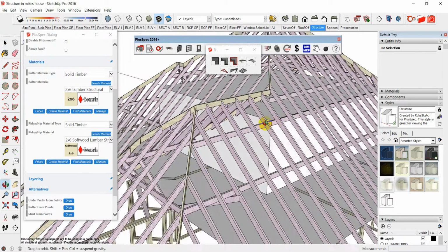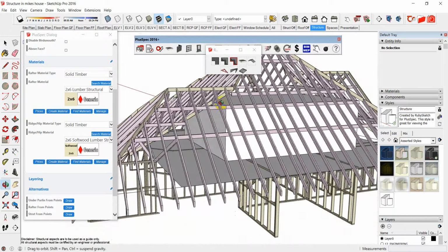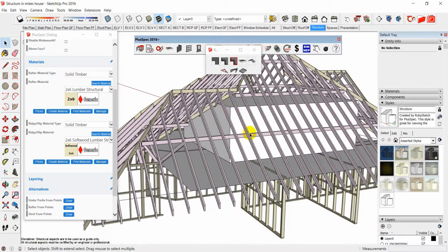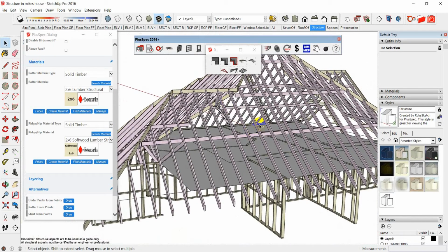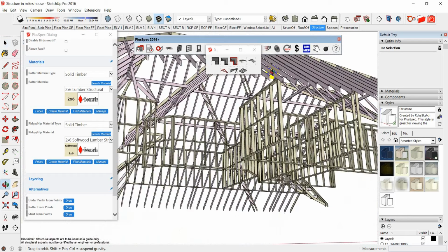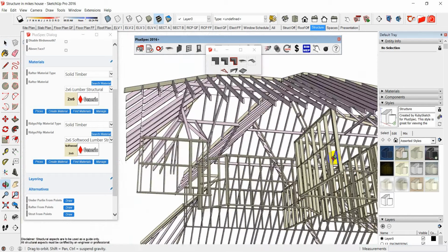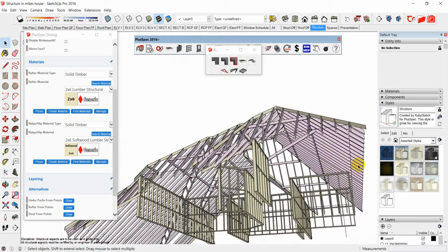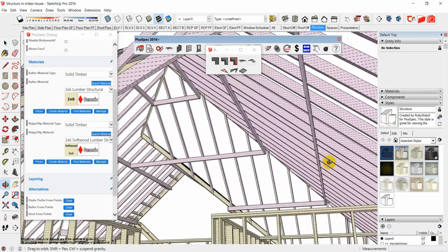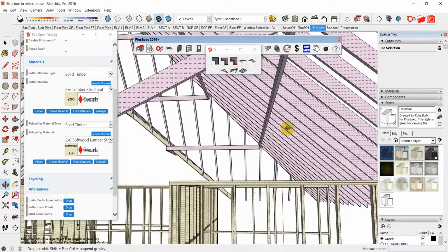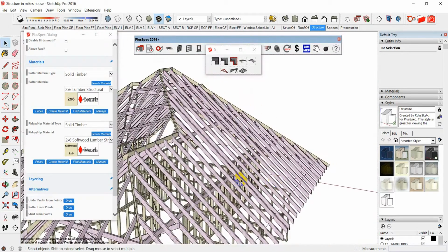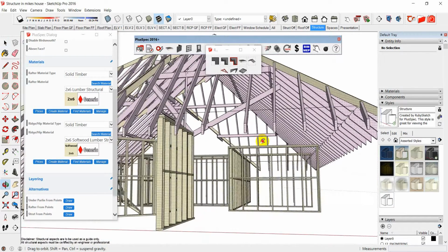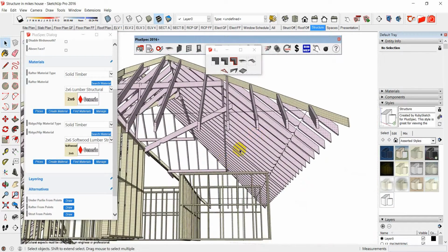And sometimes the underpurlin might have to span further because, I'm going to undo that. Let's see if I can explain this for you. Get rid of this face. Sometimes it's going to be a lot longer before I can get to the next wall. So I'm going to use the underpurlins I put in here. I like to over-engineer things a little bit, not getting too carried away. And basically I just like to divide the overall span by 3, which means that I've got a stronger house and a happier client, I gather.